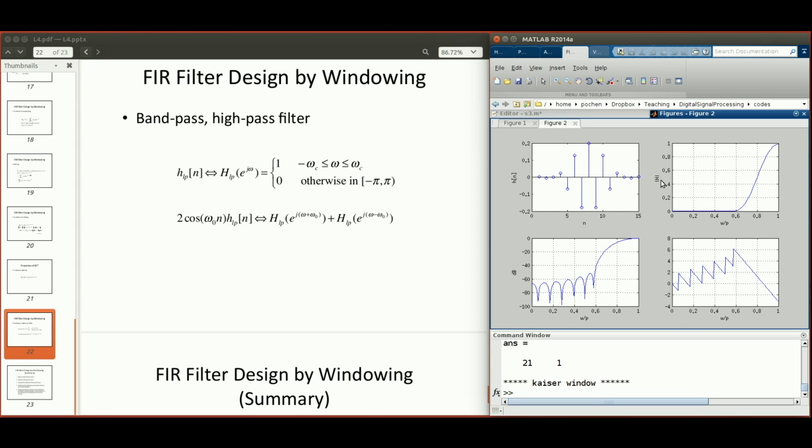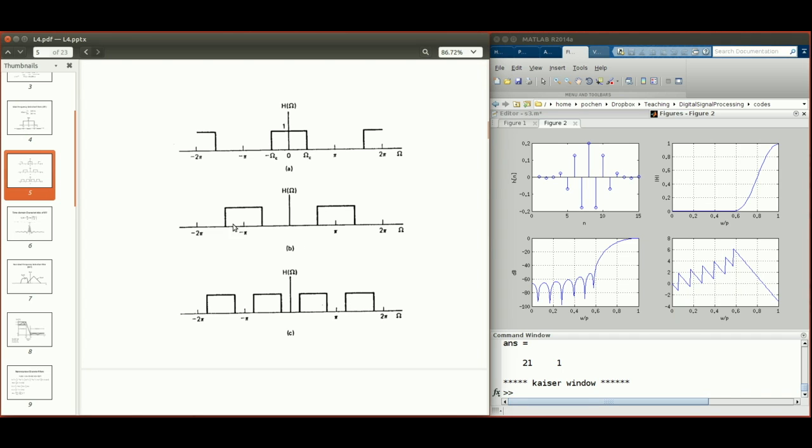And then that's the absolute value of the frequency domain representation of the filter, and you can see it's actually centered at 1. And you can see the shape: it's suppressing zero frequency and enhancing high frequency. The horizontal axis is frequency normalized by pi, so 1 corresponds to pi. If you compare this figure with our diagram for a high pass filter, that's a boxcar centered around pi.